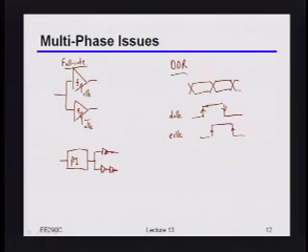Okay, so now the question is, how am I going to build this? How am I going to support this in my CDR hardware? And first of all, what are some of the options that I might have? And remember that this data clock is not really a fixed phase position. It's actually moving around based upon my CDR updates, and you want that edge clock to also move around the same way. So how might you build this? And you just interpolate from the phase interpolator again? Interpolate from the phase interpolator. What exactly do you mean? What I mean is, can you use the same 4 phase inputs and generate the edge clock also? Okay, yeah, absolutely. So you could indeed, right?